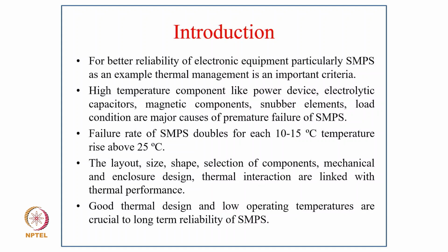Coming to the introduction, for better reliability of electronics equipment, particularly switch mode power supply, thermal management is a very important criterion. High temperature components like power devices, electrolytic capacitors, magnetic components, and load conditions are major causes of premature failure of switch mode power supply. And the failure rate of switch mode power supply doubles for every 10 to 15 degrees Celsius temperature rise above 25 degrees Celsius.